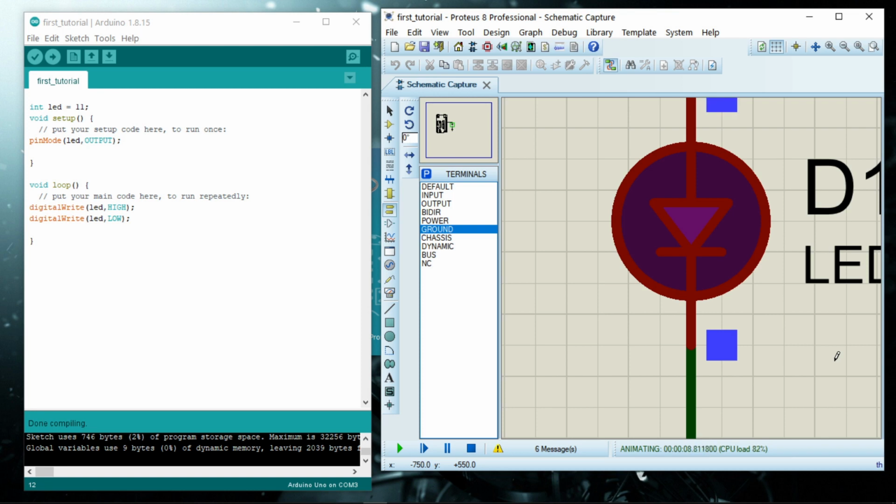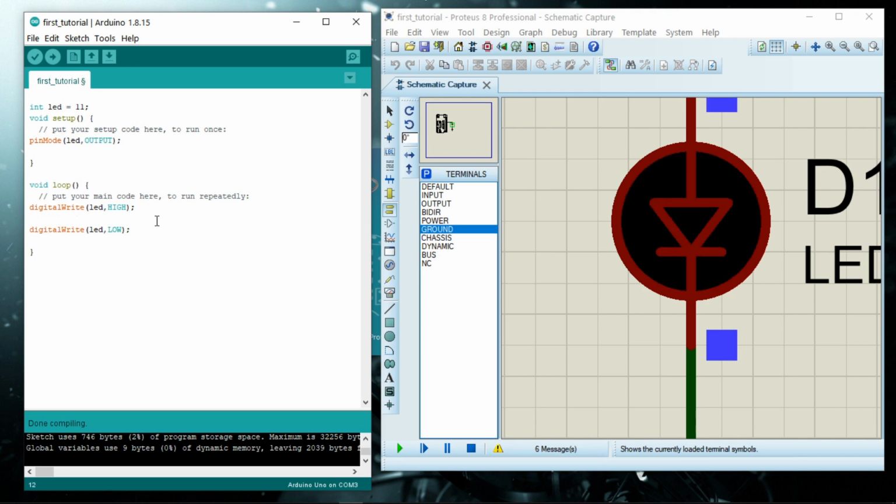So one thing you need to do is to put a delay for a particular time frame, because our eyes can only recognize up to certain nanoseconds, I think. So we have to put a delay, and it is in milliseconds. We want it in seconds, and we know that 1,000 milliseconds make 1 second.